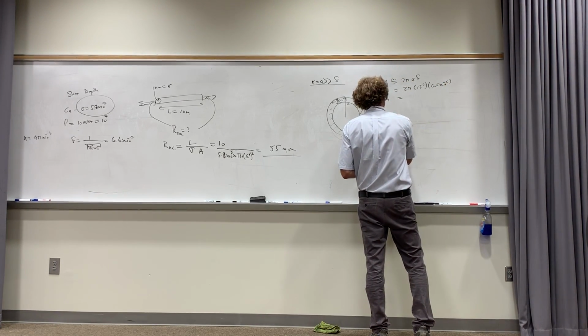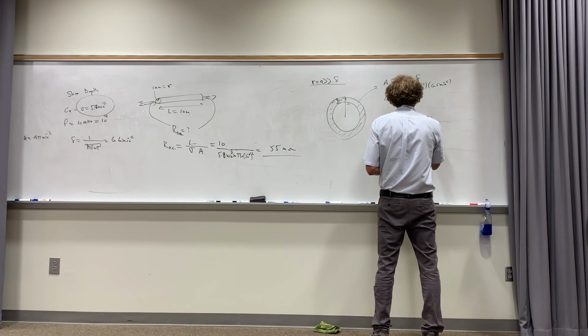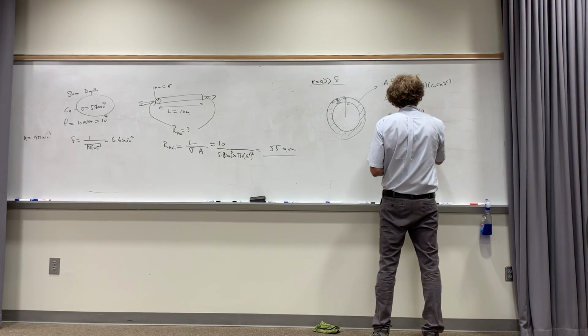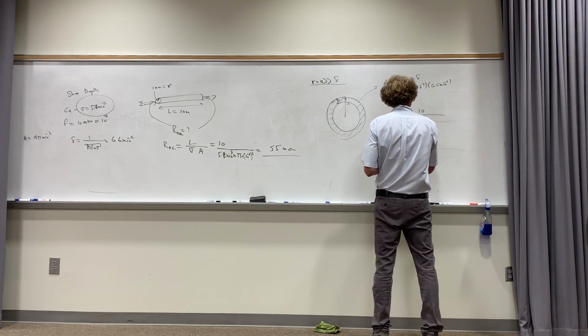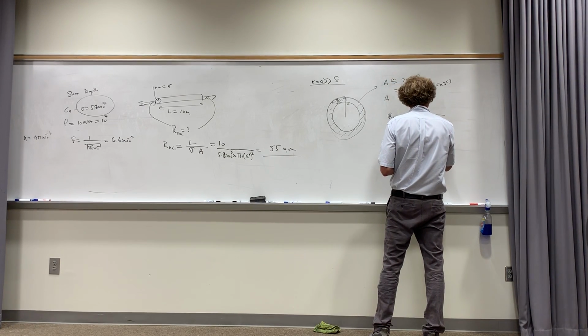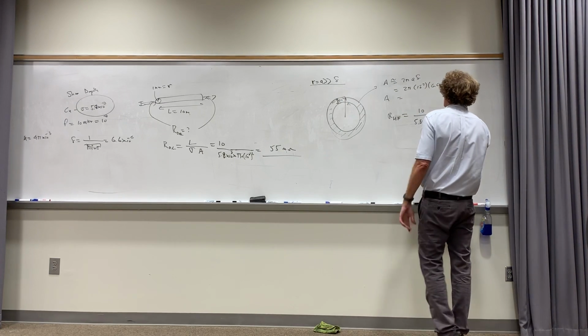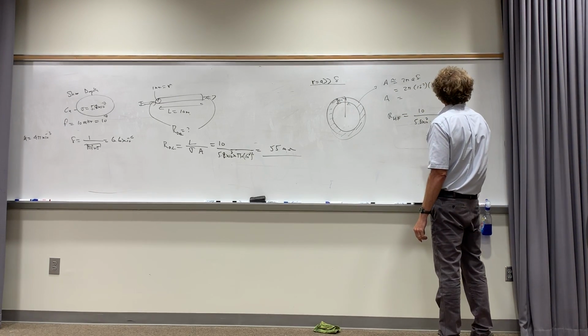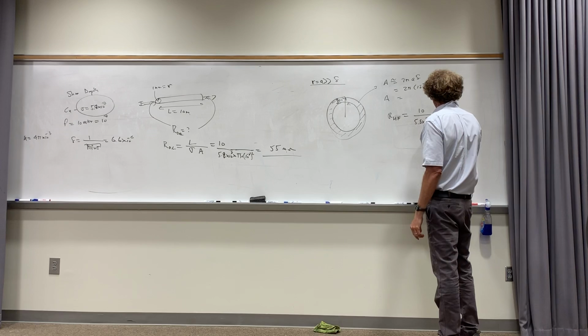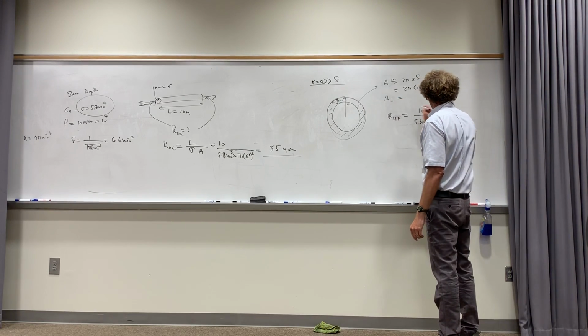Now look at the resistance, I mean RAC, actually call it RHF, high frequency. It's still a length of 10, over sigma 5.8 times 10 to the 7th, but now the area is down to whatever that is. That's about 10 to the minus 9, so call it area high frequency. Can you give me this?